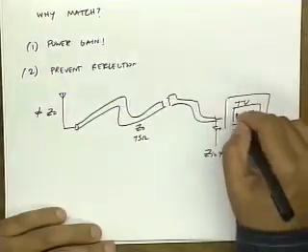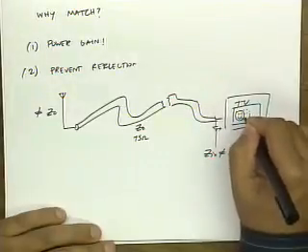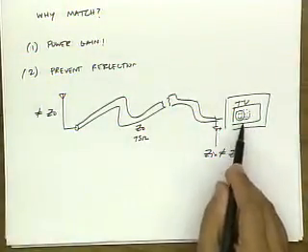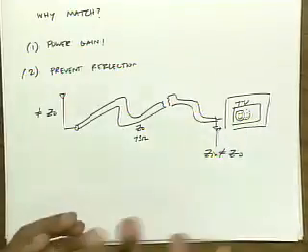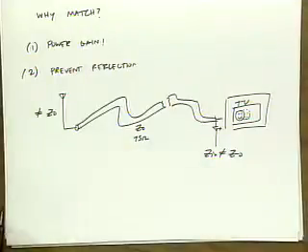So when the new signal arrives, what does it look like on the screen? It's a ghost, right? Because there's a time delay between the real signal and the reflection, you actually see a ghost. And since there are multiple reflections, you might see multiple ghosts, or you might see a fuzzy ghost. Go try this at home. It's kind of neat. Introduce a mismatch and watch what happens on the screen.